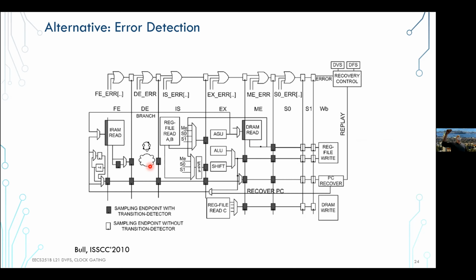So the first thing you want to do is, again, give yourself more slack toward higher performance. So you boost the voltage. The circuit operates faster for a given frequency. Then you increase the frequency to close the slack. So this ordering has to be basically built into the algorithm so that it knows what to do first.